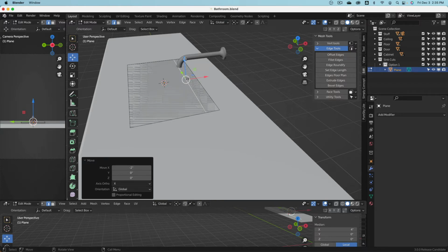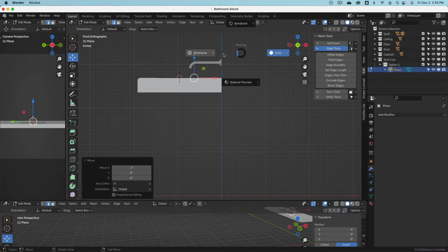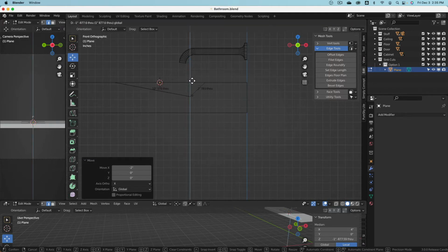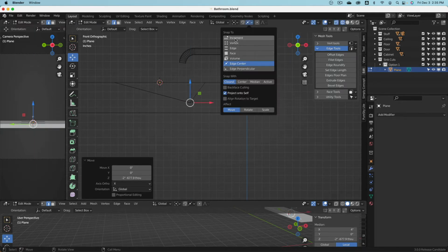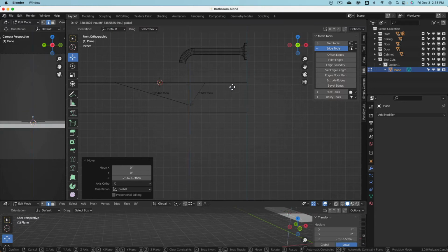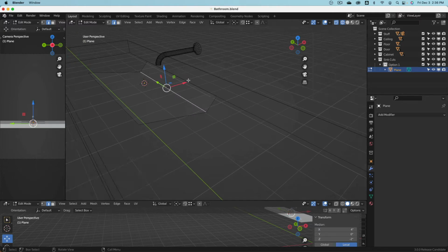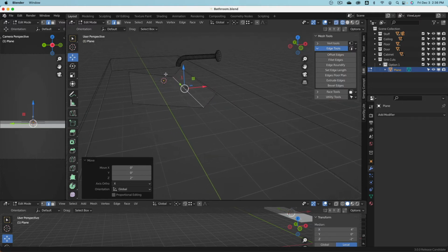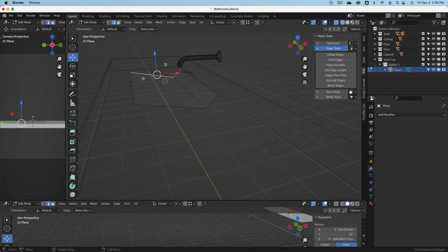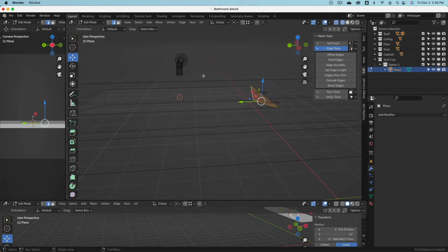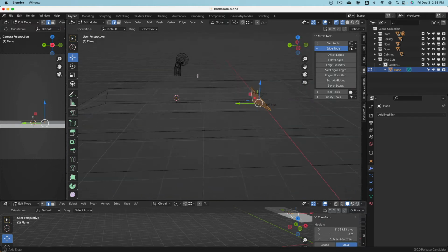Then we can go to a side view, Z and wireframe, and now I can think about how far do I bring this one down? I turn on vertex select, move this one down, hold Control, snap to there. Then I move this one up by maybe 2 inches. Yeah, that looks pretty good. Okay, very nice. So this is now an interesting surface. I select these two faces and F, select these two faces and F. Very good. Yeah, that's nice.